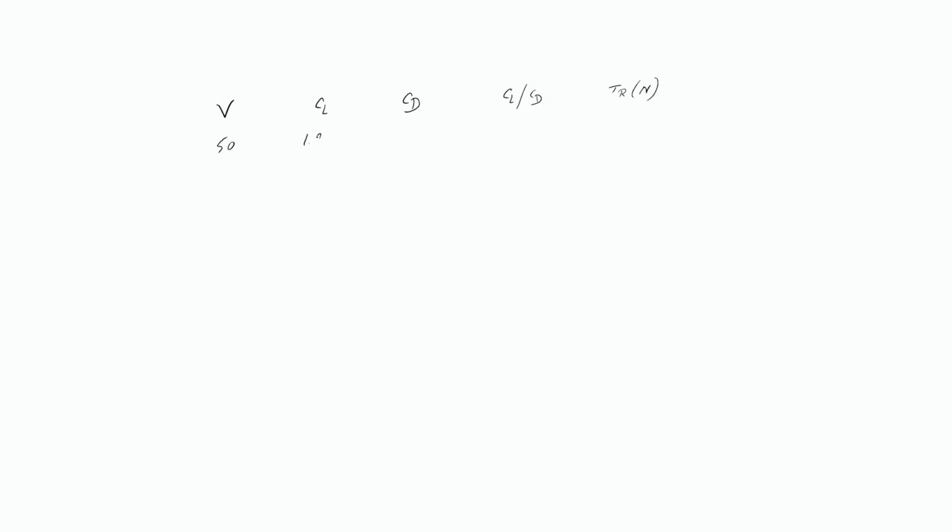CL required was 1.9493. 0.1868 was the drag coefficient. CL by CD was 10.4352 and thrust required was 8449.9338, which is in newtons.